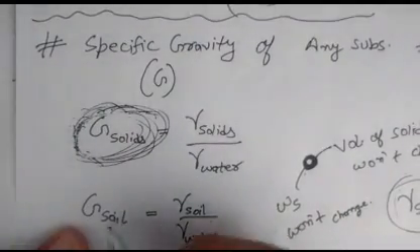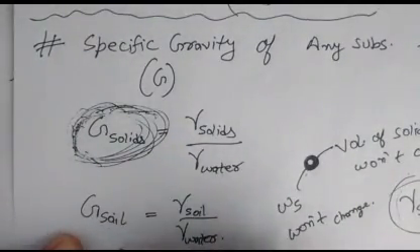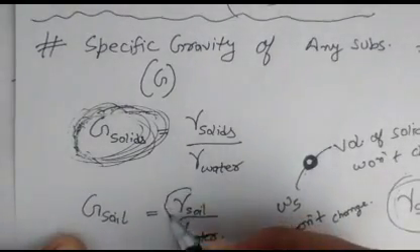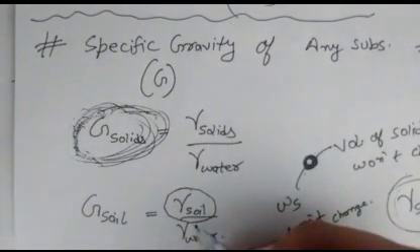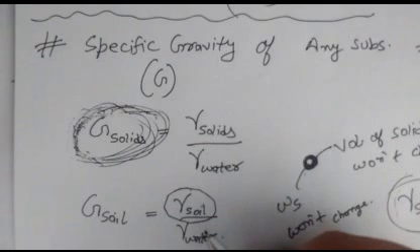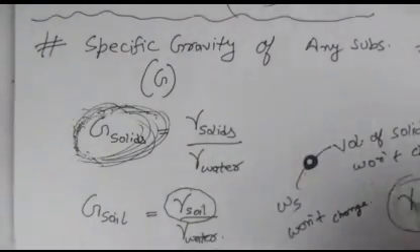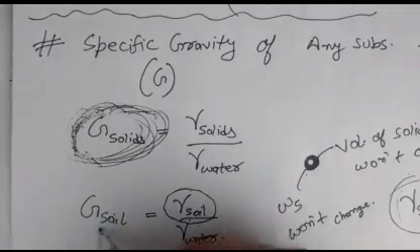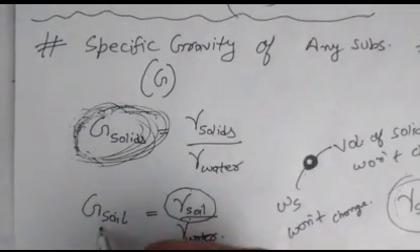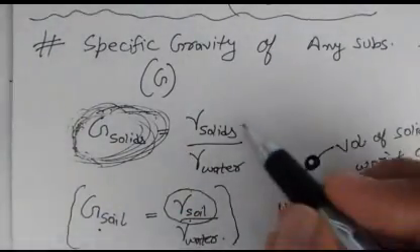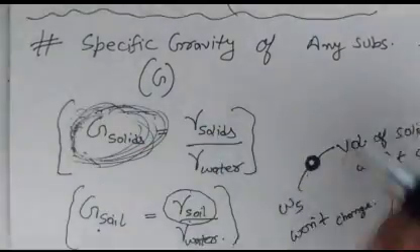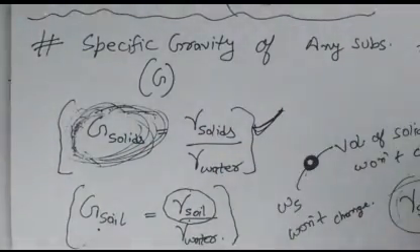And when we talk about specific gravity of soil, we actually don't use this, because the issue here is that this gamma of soil keeps on changing, since it also includes weight of water, volume of water, and volume of air. So on changing the soil composition, like density, or the voids of the soil, this gamma soil will change, and correspondingly the specific gravity of soil will change. So we rarely include this in solving our questions, but G of solids, specific gravity of solids, is the best way to solve the questions.